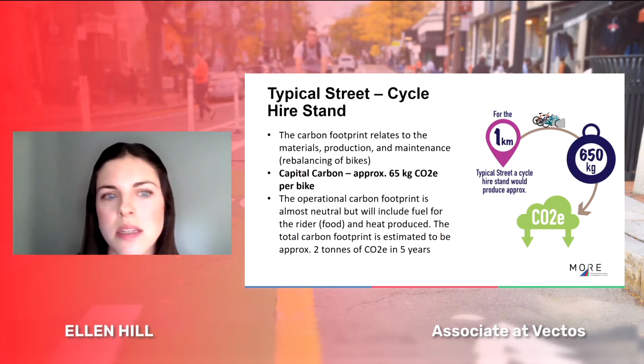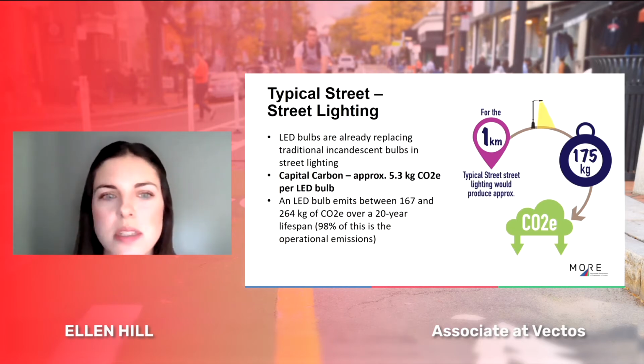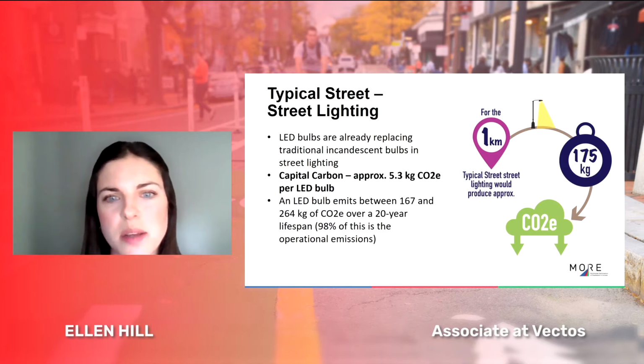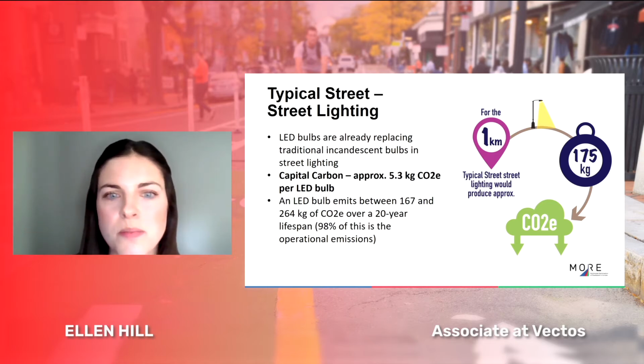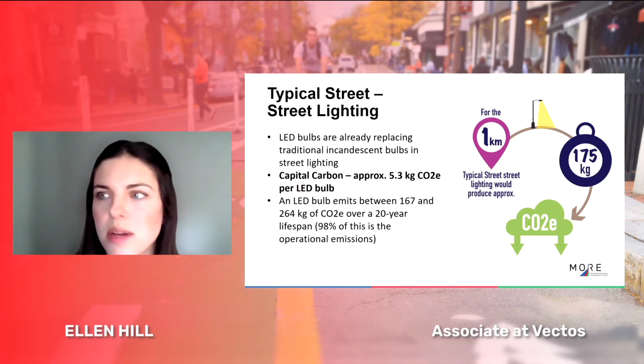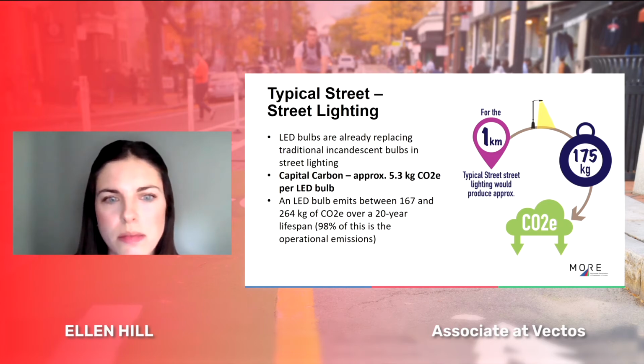Next slide. So LED bulbs, looking at street lighting, are already replacing incandescent bulbs in many places, with 55% of all bulbs now used in the UK being LED. The capital carbon impact of an LED bulb is on average 5.3 kilograms of CO2e. However, this does not include the lighting column or other elements such as maintenance. Based on 30-metre spacing, the impact on the typical street is therefore 175 kilograms of CO2e.